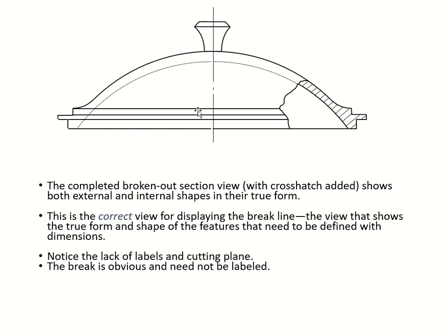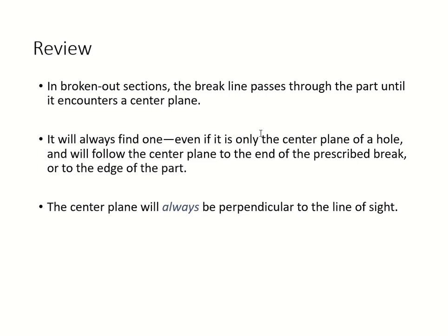The front plane is here, and since this is in 2D, it's a little bit difficult to see the depth of it. So you can either project a top view or a right view to see the depth of this front view. So what we see are two planes: that's the front plane, and this one is the center plane. And you definitely need to go all the way to the center plane when you're fracturing or breaking this model. And that's what it's saying right here.